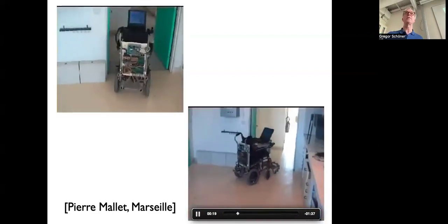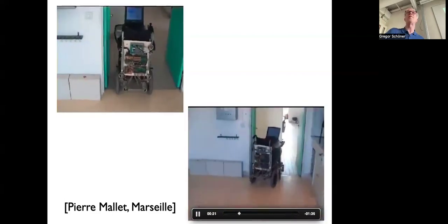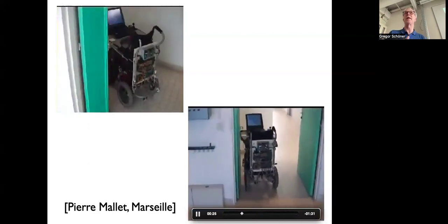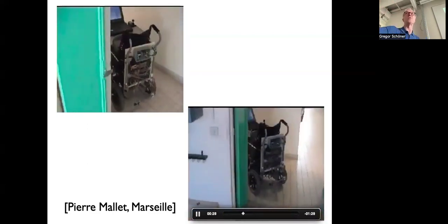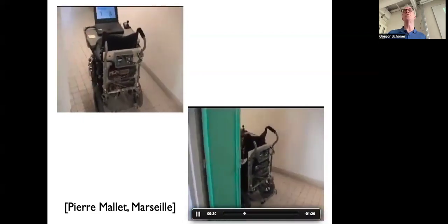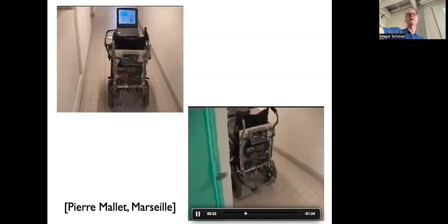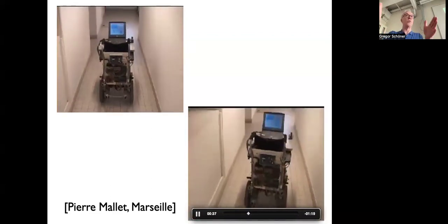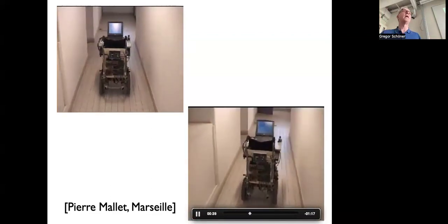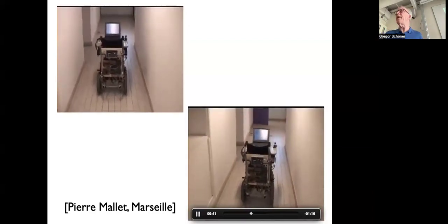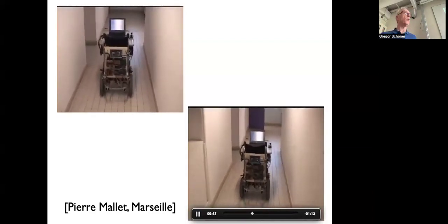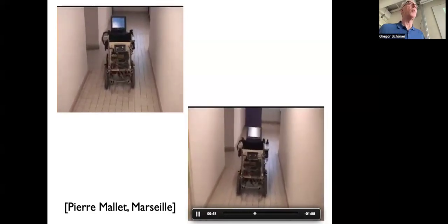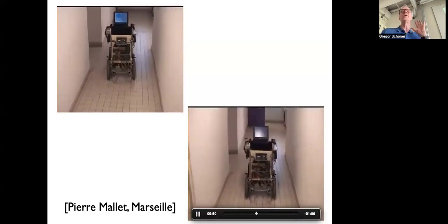It has these walls, and it will be doing this wall following. And as soon as there's some opening in the wall, it will go through that opening if the obstacle pushes this way. So for instance, if you wanted to go into a room, you would just put the target inside that room, and it would be driving along the wall until there's a door to that room, and then returning. So even though it's just local, extremely low level, very stupid, emergently it does something reasonable that almost looks like planning, but it doesn't really need to navigate.